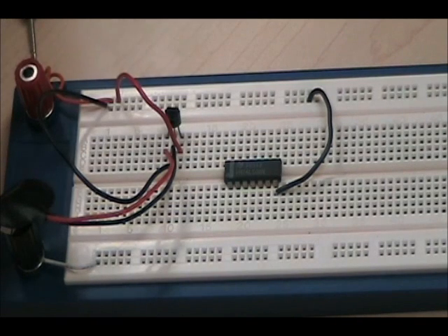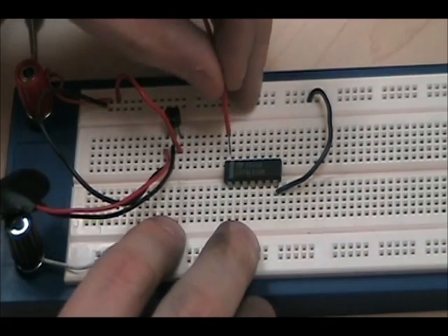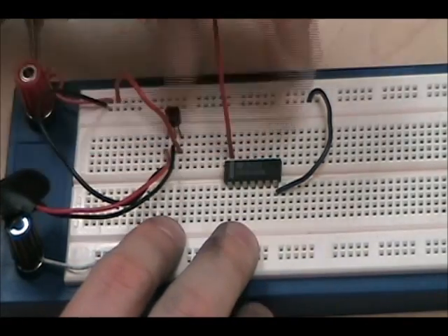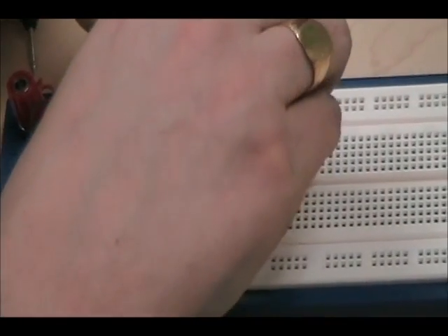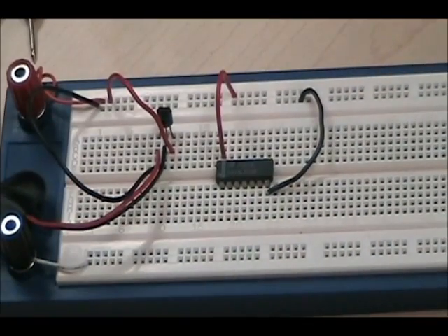Step 2 is to connect power to it. Now keep in mind, we are not plugging in our battery just yet. Normally I'd be using much shorter wires, but I'm just using what's available. So that will go to our top rail, our power rail. There we go. It's now officially connected to our 5-volt line.